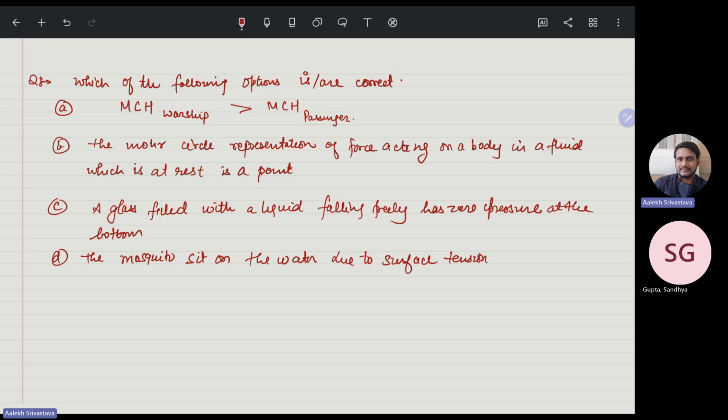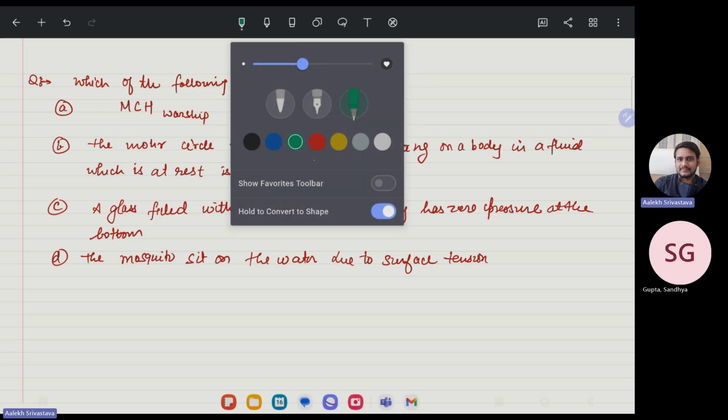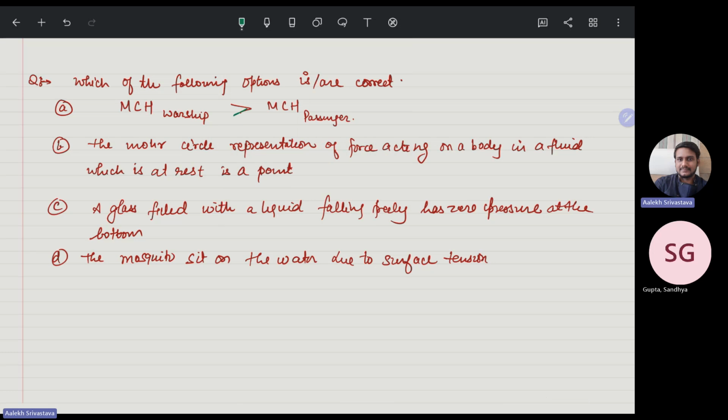So the metacentric height decides the stability of any object that is partially submerged in a liquid. If the metacentric height is large, that would lead to discomfort and a larger amount of oscillations. Therefore, the metacentric height of passenger ships is kept low so that their comfort can be provided, although safety is a little bit compromised. But for warships, safety is the prior thing. So the metacentric height of a warship is greater than that of a passenger ship. That answer is correct.